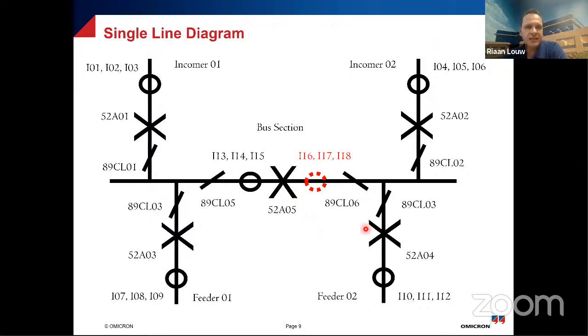So all of this is done internally to the relay logic, and at the end of the day, we would just need to test this system by simulating fault conditions in zone 1, zone 2, and then obviously that's a very tricky one in this dead zone that we have over here between the breaker and the CT. We will also be simulating that for our exercise today.